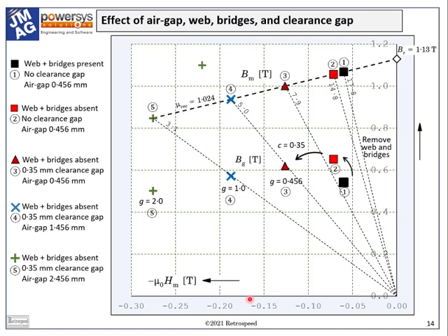Now, the recoil line here is not at 45 degrees because of the greatly expanded scale on the axis of magnetizing force. But that's what this is, a recoil line. The knee is way off to the left, or we hope it is, and we're working at a comfortable temperature, not 150 degrees C. Let the operating point fall over that knee, and we're in trouble.